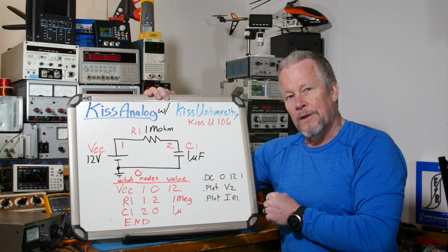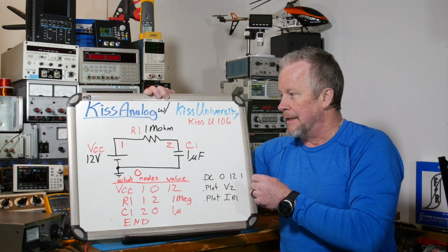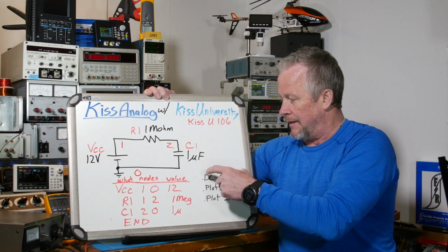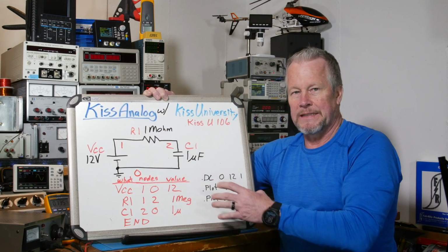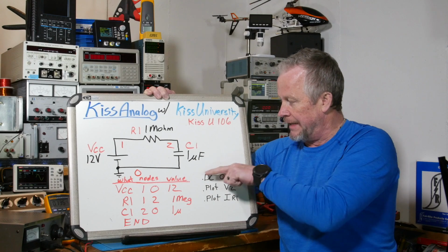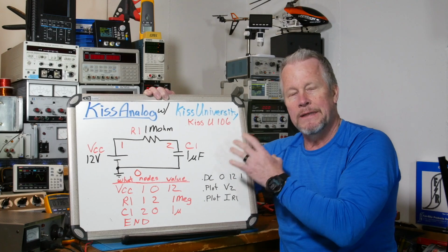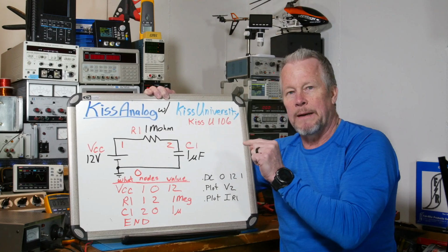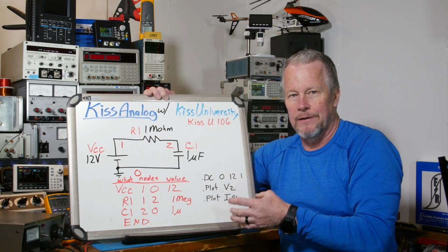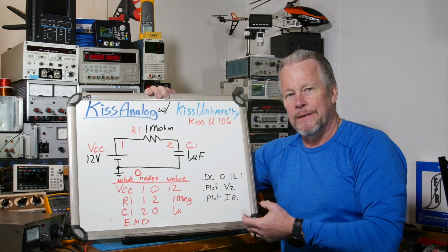Okay, well, one of the cool things that happened with MicroCap and Intusoft, and I think PSpice did it too, is once you run the program and it runs through all this stuff and plots and prints out all this stuff, there's also another mode that you can go into. You can say, just do the analysis part, and then give me basically like a scope, give me a graph, and then I'm going to use my probe and probe the points that I want you to plot. So that's interactive. Instead of setting it all up and then hitting a button saying go, it allows you to interact with it.